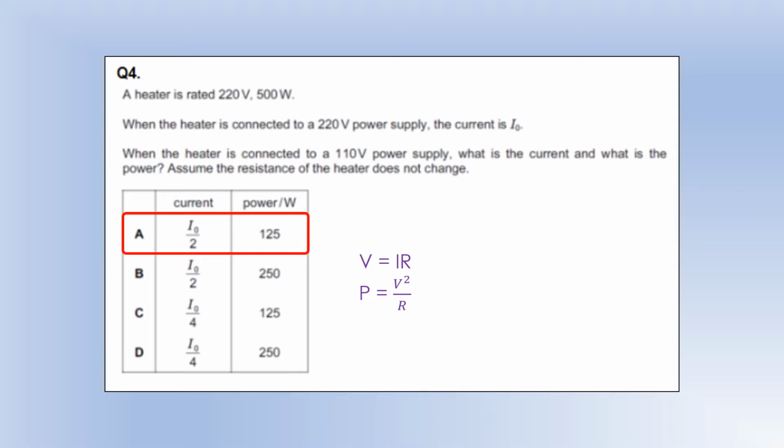And this is the reason if you take a hairdryer across to America, it won't work very well, because if you buy it in Europe, it's designed for about 230 volts, and if you hop over to America, it's now supplying it with 110, so you get sort of 1/4 of the power output, which isn't great.